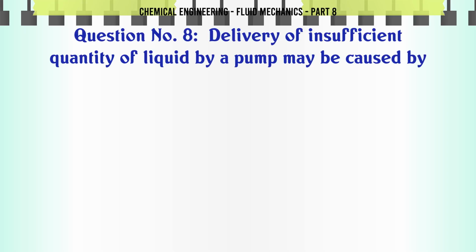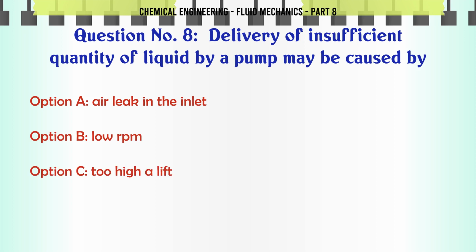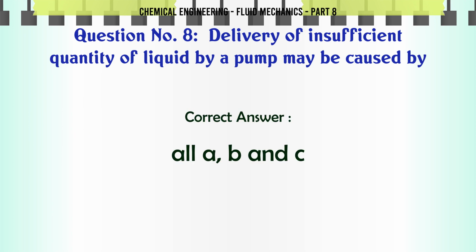Delivery of insufficient quantity of liquid by a pump may be caused by: A. air leak in the inlet, B. low RPM, C. too high a lift, D. all A, B, and C. The correct answer is all A, B, and C.